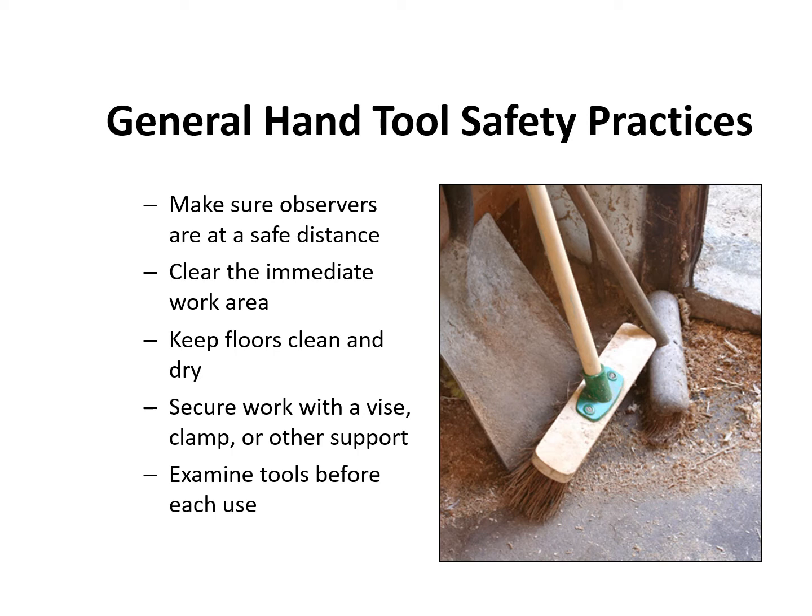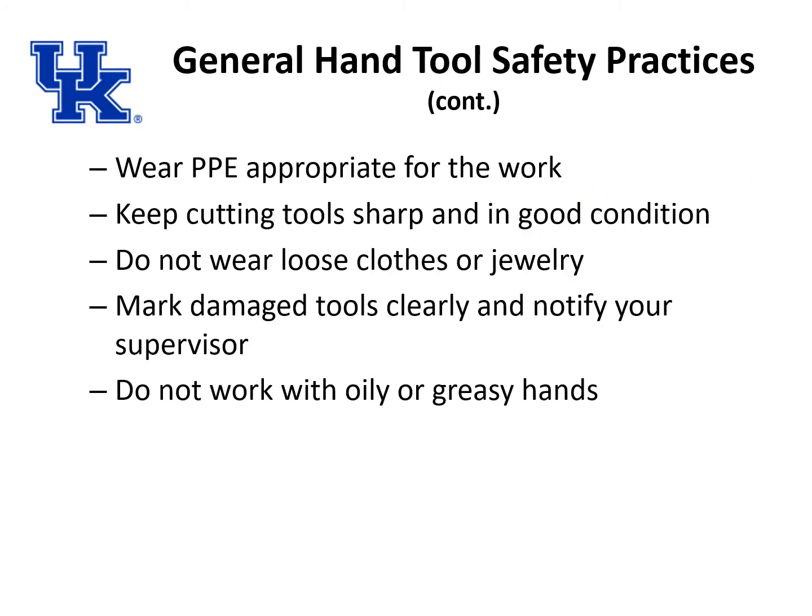Examine tools before each use for defects or signs of damage. When using hand tools, wear appropriate personal protective equipment, including safety glasses, work gloves, and work boots with steel toes. Keep cutting tools sharp, well lubricated, and in good condition to be sure they work properly. Never wear loose clothing or jewelry, and tie back long hair when using hand tools. Mark damaged tools clearly and notify your supervisor.